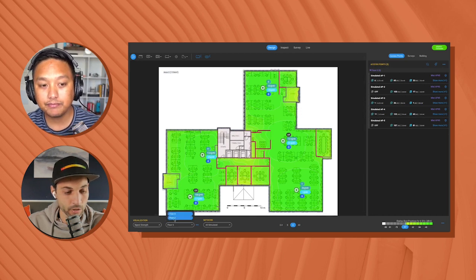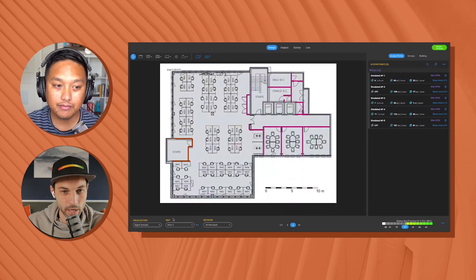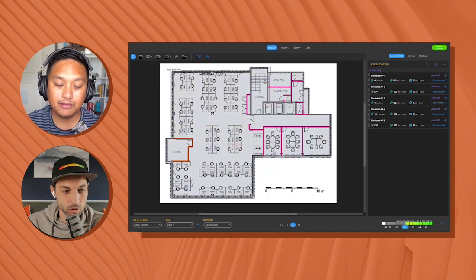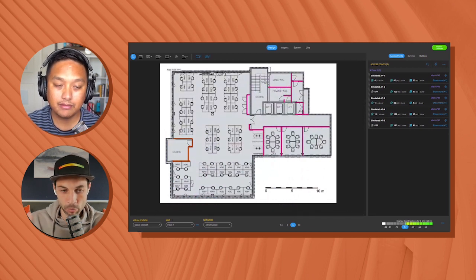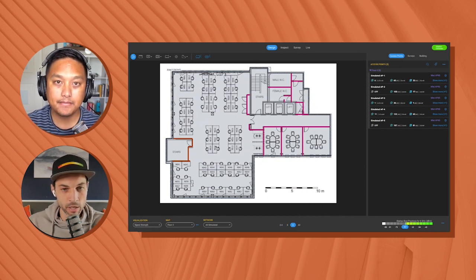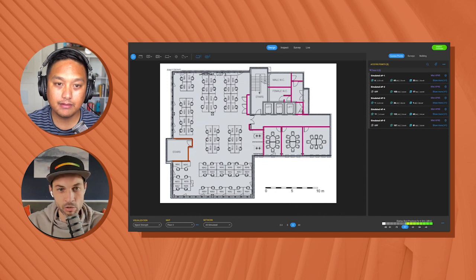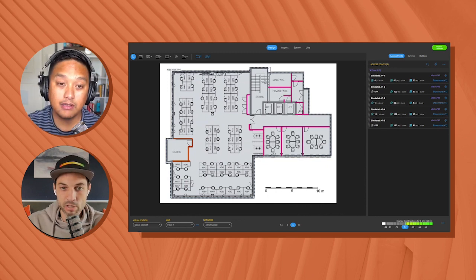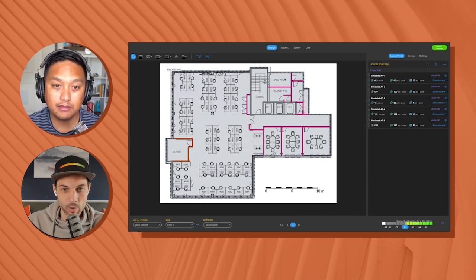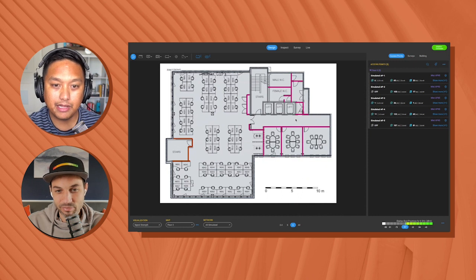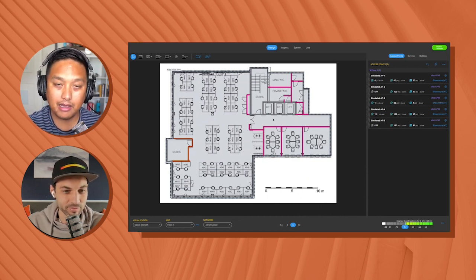If we move on to the other floor that we have, on this floor we also imported, scaled it, drew the walls, and drew the coverage area. But here we didn't draw any exclusion areas. We have a section with stairs, lifts, and restrooms. And it's important to know that it didn't even place the APs on this floor when you ran AI Auto Planner.